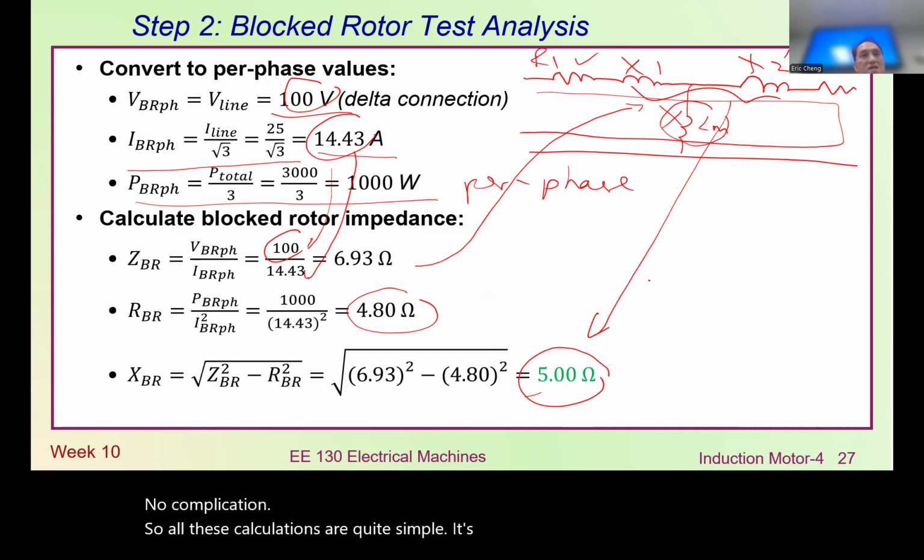As I say, for motor design, we can only measure the total. You can see that the current path here is flowing in this way. No way we can know which one is which because they connect in series. So the only way depends mainly on motor design. For good motor design, we use half-half. That means 50% will go to X1, 50% go to X2 dash.